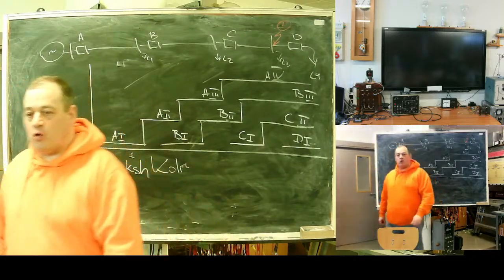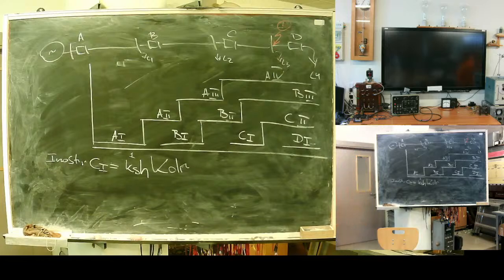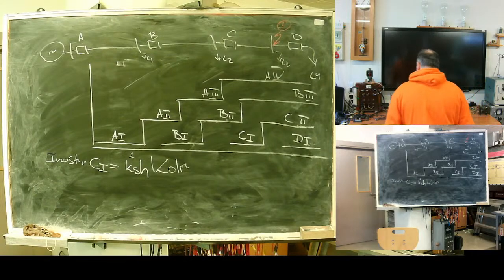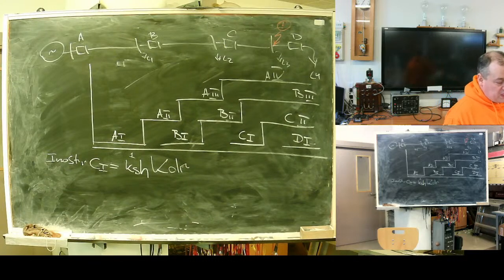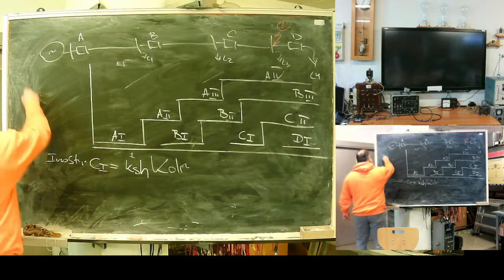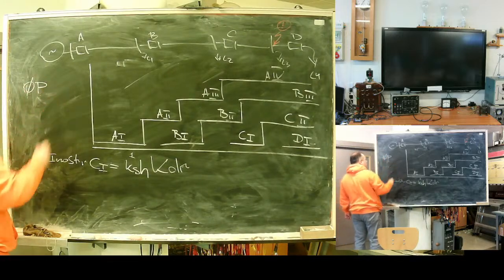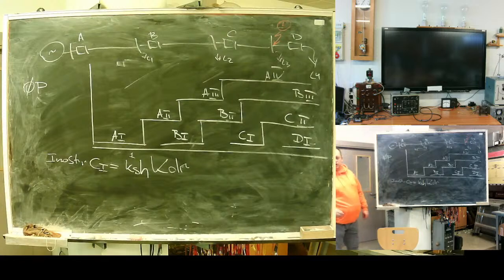What's this? It's from Latvian drošums, the factor of safety. First, it depends on what kind of transformer, what the precision of your transformer is. If you have an ordinary 10P, P means protection. What does 10 mean? 10% error. If you have ordinary transformers with precision class 10P, this means they are with an error of 10%.